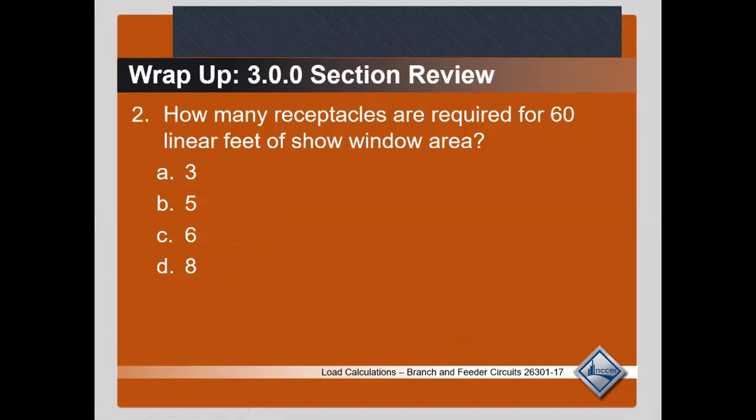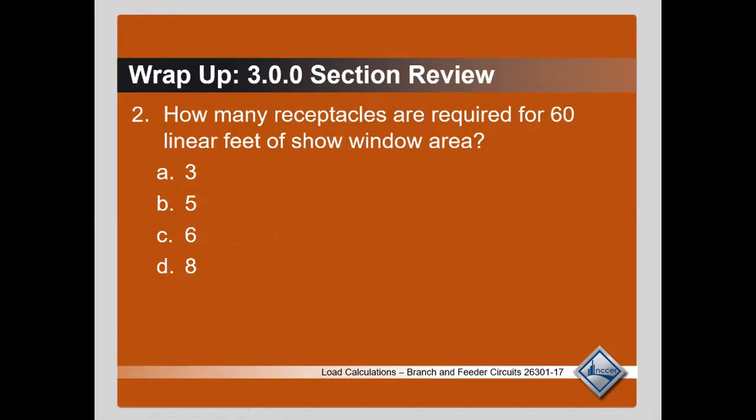How many receptacles are required for 60 lineal feet of show window area? Remember, you're only required to have one outlet per 12 feet.